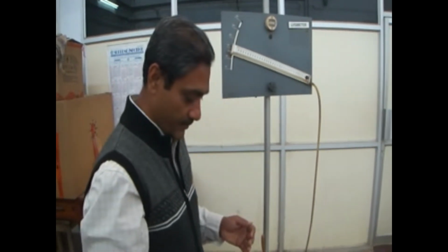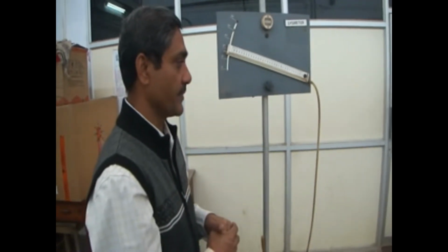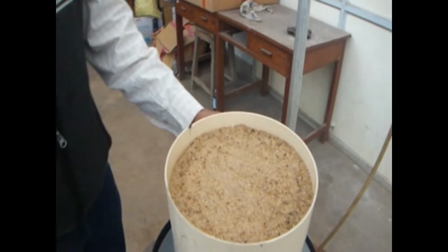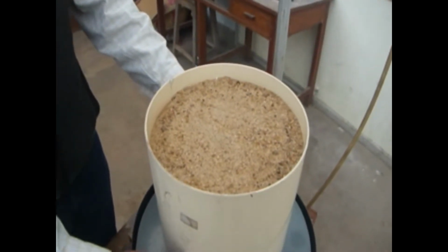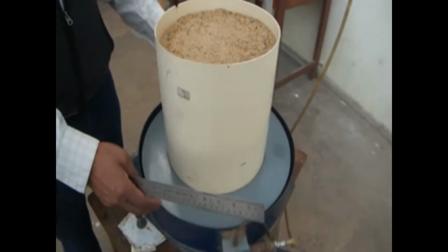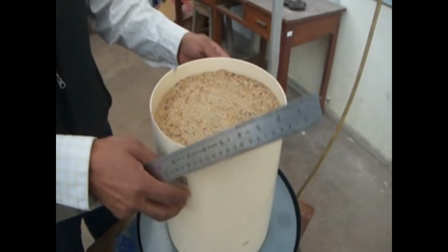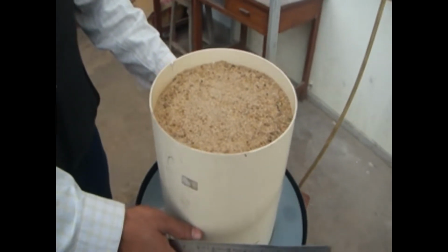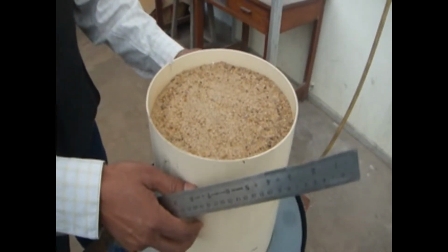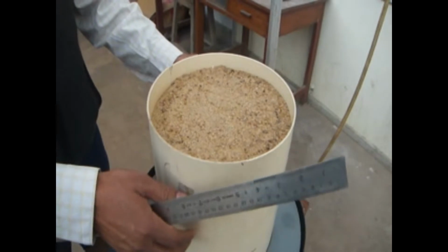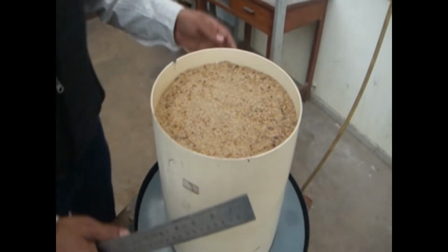So let us put the cylinder filled with sand, and before that we need to find out the measurements. Yeah. So this is the complete setup. We have a weighing platform with hydraulic balance. We have a sand filled cylinder that is resembling the container filled with actual field condition soil, and we need to find out what is the initial weight. So the initial weight we can see here, whatever the initial condition is, suppose 50.